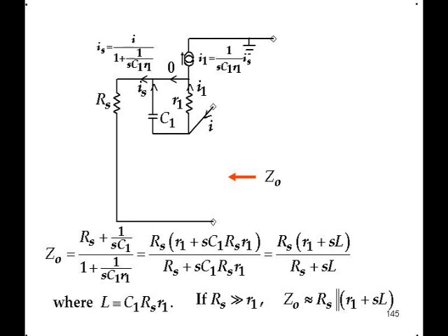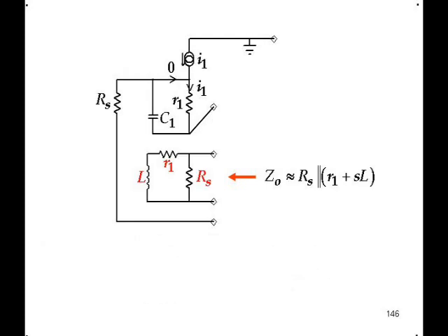What that means physically is if you look into the source of a source follower, the signal resistance RS looks like an inductance over a certain frequency range. That's impedance reflection factor. The impedance reflection ratio is frequency dependent because of the C1. That's what makes the RS convert to an effective inductance. So there's the equivalent circuit model that represents that equation.